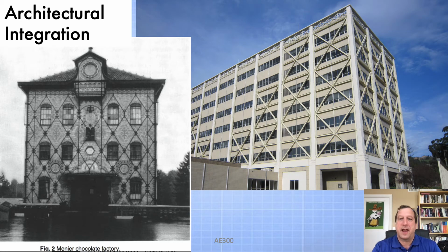On the right-hand side, what we have is actually a building that is in an earthquake zone, California, near San Francisco. And what's interesting here is, again, they're proudly showing off the X-brace, and they're showing that you need more X-bracing as you get lower on the building because the lateral loads accumulate as you move down the structure. Now, what they're not showing you is that those X-braces will require painting and maintenance for the entire life, and will collect pigeon poo and seagulls and snow and icicles if they were in different climates than California.